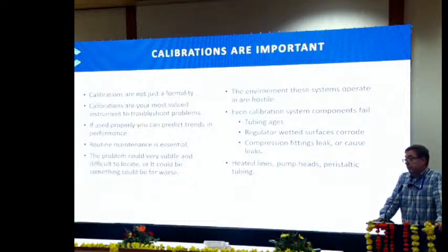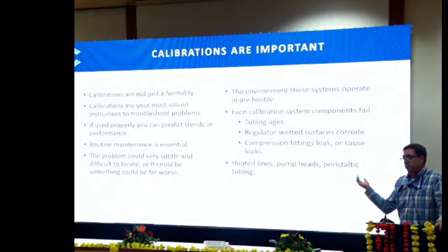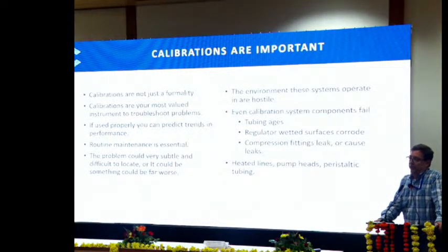You can predict trends in performance. You can start to see excessive drift. If you're using a chemiluminescent analyzer, for example, for NOx, you can start to see when the photomultiplier tube is starting to decay. I mean, there are some good things there.